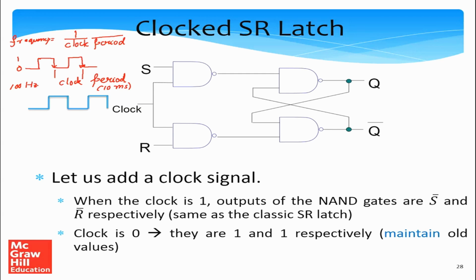So let's say if I buy a new machine or a laptop or a desktop, and the frequency is, let's say, 2 gigahertz, what this means is that every half nanosecond or 500 picoseconds, we have a negative edge of the clock. And all digital elements inside a processor, and including all the designers who are designing them, coordinate all their actions with respect to the negative edge of the clock.